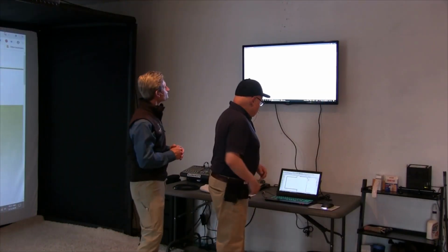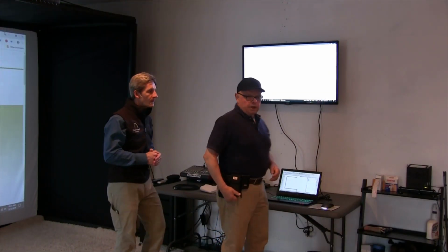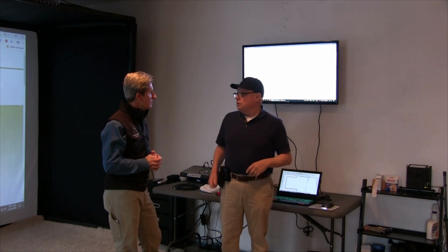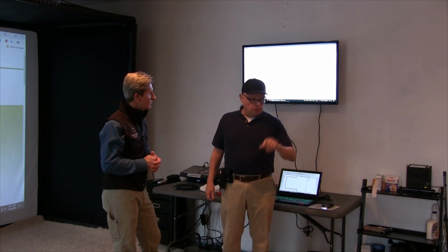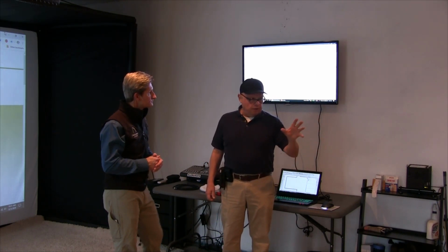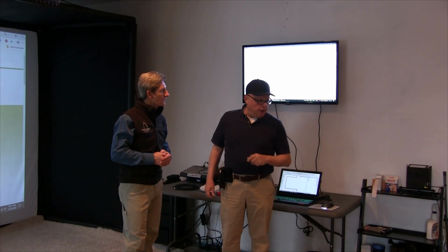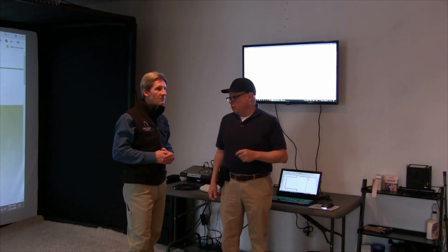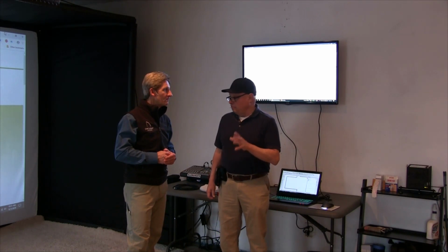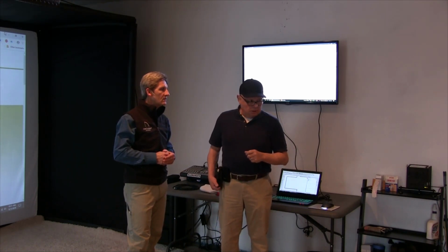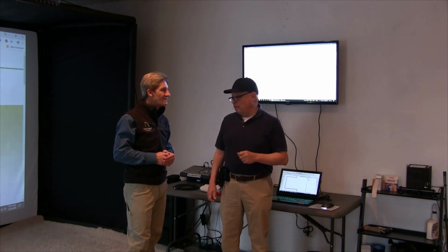Okay, so at this point, we go to work with the laser, and we just start taking the dimensions across, and we locate all the walls. We'll be taking all the dimensions that we need to create this space. We're going to try for an accuracy of plus or minus 1/8 of an inch. If we can get it, we'll get even more accurate. The laser equipment from Leica is very accurate, and they can get down to 1/16 of an inch.